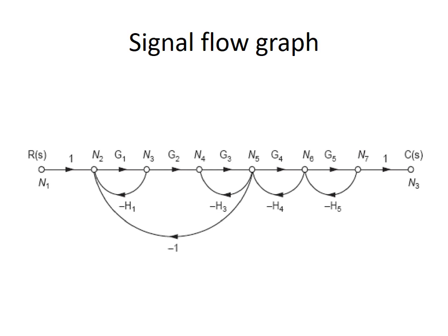Again, the forward path is G1, G2, G3, G4, G5. You have only one forward path, and the remaining ones are all feedback paths. Like this, you have to find individually how many forward paths you have and what the forward path gain is, and then the individual loop gains, the products of two possible combinations of non-touching loops, and the products of three possible combinations of non-touching loops.